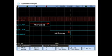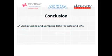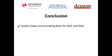By further zooming into the waveforms, you should be able to observe that there are 16 clock pulses from the rising edge of ADC to the falling edge of DAC. You should also observe that there are 16 clock pulses from the falling edge of ADC to the rising edge of enabled signal.